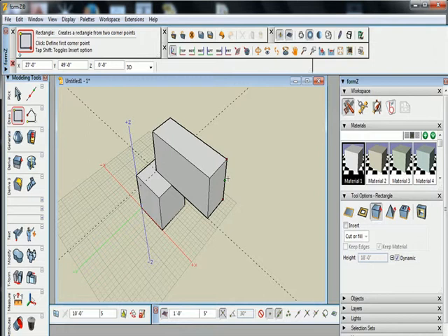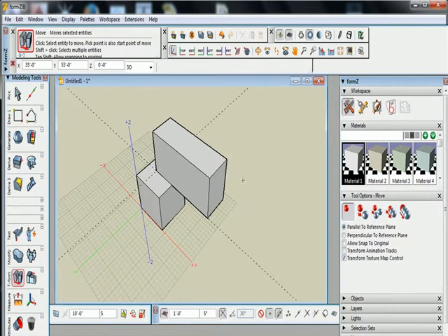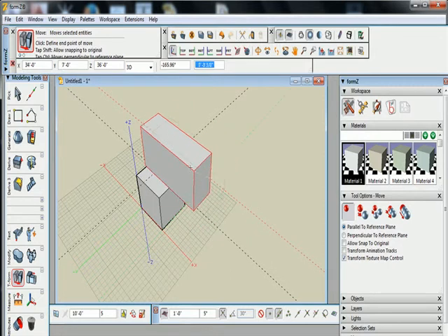And notice that this box is intersected with the first box, right? So all we have to do is move this down. Just like how we moved the grid, we are going to go to the transform tool, move, select one of the corners of the cube, and this time I'm stuck on the XY plane, right?